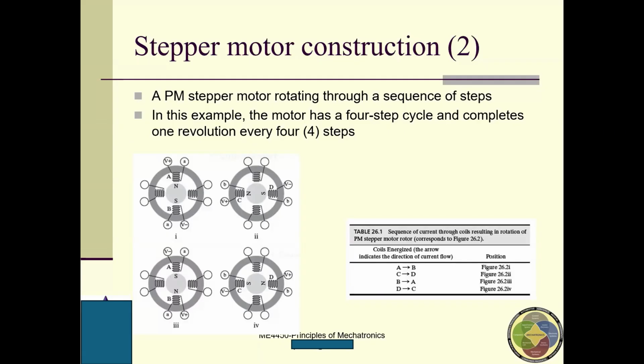Then I can use my right-hand rule this way, because this is the current direction. My thumb goes up, which means here will be the north pole of this newly generated field, and here will be the south pole of the newly generated field. You agree?